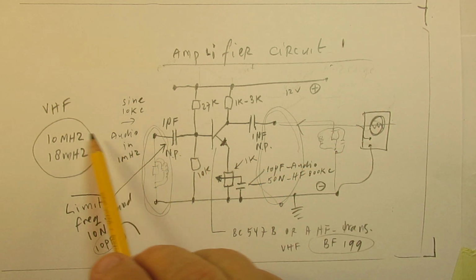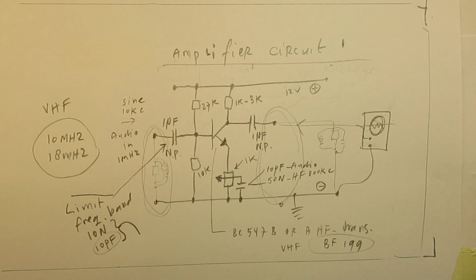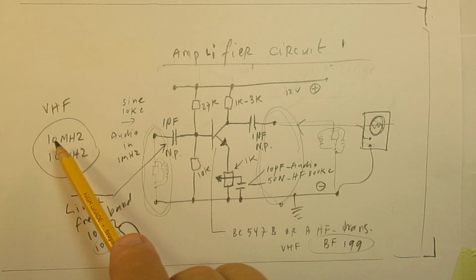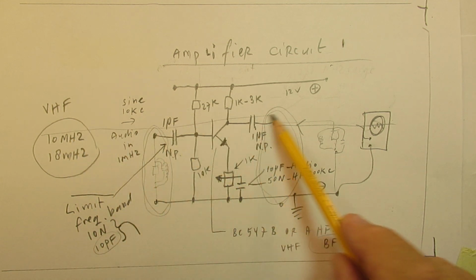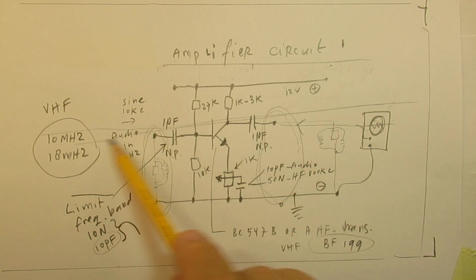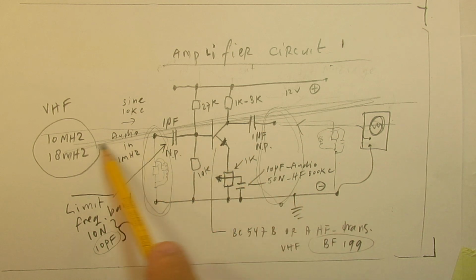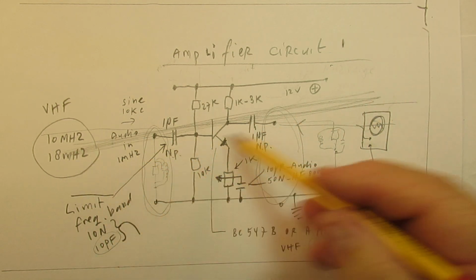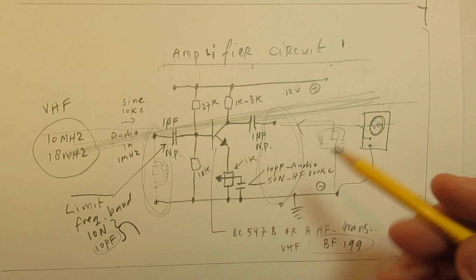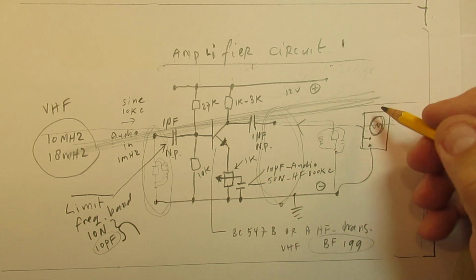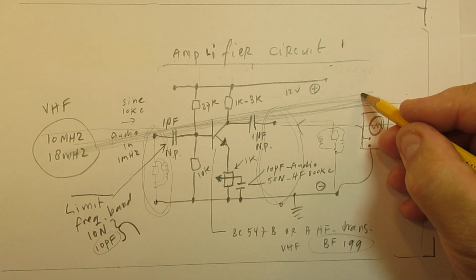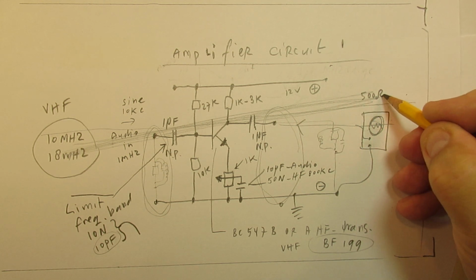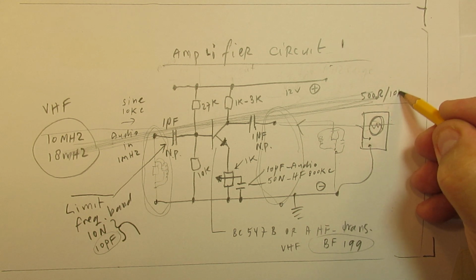The overall impedance in a broad sense, so coming from audio amplifiers, input, output. So this is very sloppy, but I only want to give the idea. The overall impedance in audio amplifiers is in the range of 500 ohms up to 10 kilo ohms.